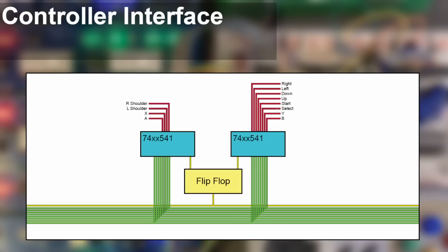Now I do want the low half to be the full 8 bits of the NES controller, but what I'm thinking is I output the other 4 bits to the low 4 bits over here, but then the top bit I pull high permanently. So then when I'm first initializing my controller code, I can just read and see which byte has the top bit set.